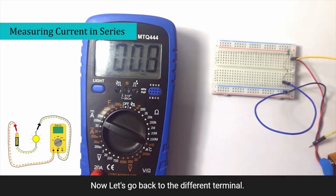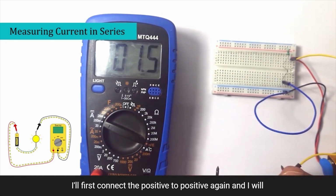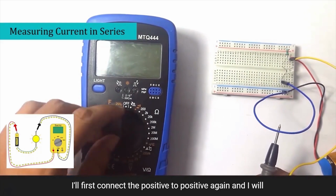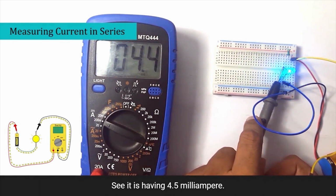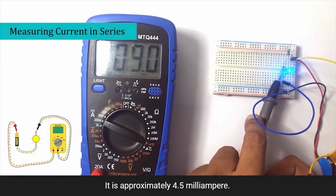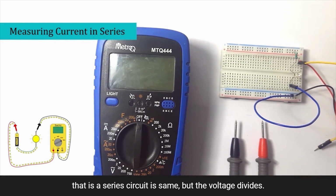Now let's go back to the different terminal. I'll first connect the positive to positive again, and I'll switch back to 200 milliampere, and I'll get back to the resistor again. See, it is having 4.5 milliampere. It is approximately 4.5 milliampere. Here you saw the current across the terminal, that is the series circuit, is the same, but the voltage divides.